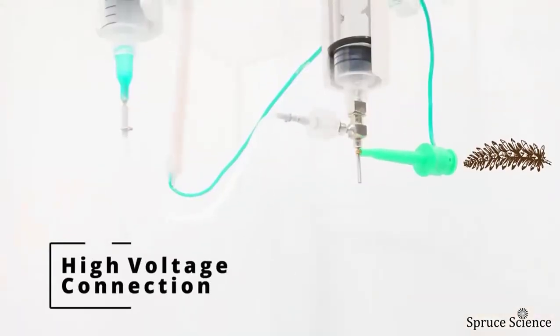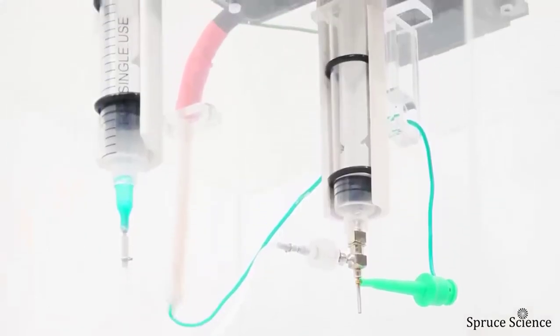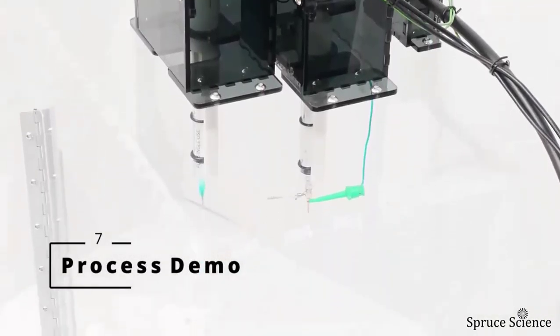To connect the high voltage output to the sample, we will be using the hook clip. Just a friendly reminder to always verify that the high voltage is off and fully discharged before touching any of the equipment. We're going to demonstrate how to use the coaxial electrospinning machine to create compound fibers.